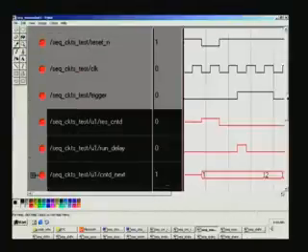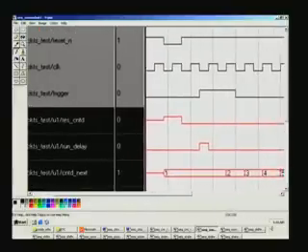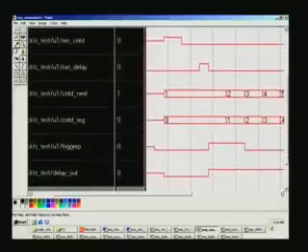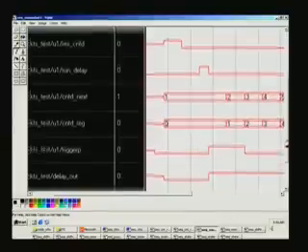If you see here, this is the trigger, and this is resetting the counter, and this run delay is the one which senses the rising edge of the trigger. The trigger is going high right at this point, and the earlier value of the trigger is 0, which must have been preserved in trigger P. You see here trigger P is actually 0 at this point, whereas it becomes 1 at the rising edge of the next clock pulse.